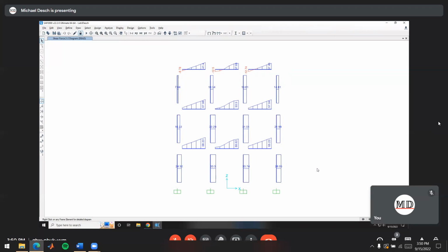And then it's going to be a nightmare for the people actually trying to build it because they're trying to figure out what beam goes where. So generally what we try and do is we try and keep them about as similar as possible as much as we can. So what we'll do here is figure out what our maximum shear is and then size all the beams on this floor to be big enough for that, to keep it efficient, but also not make every single piece different and just a nightmare to work with. Make sense?